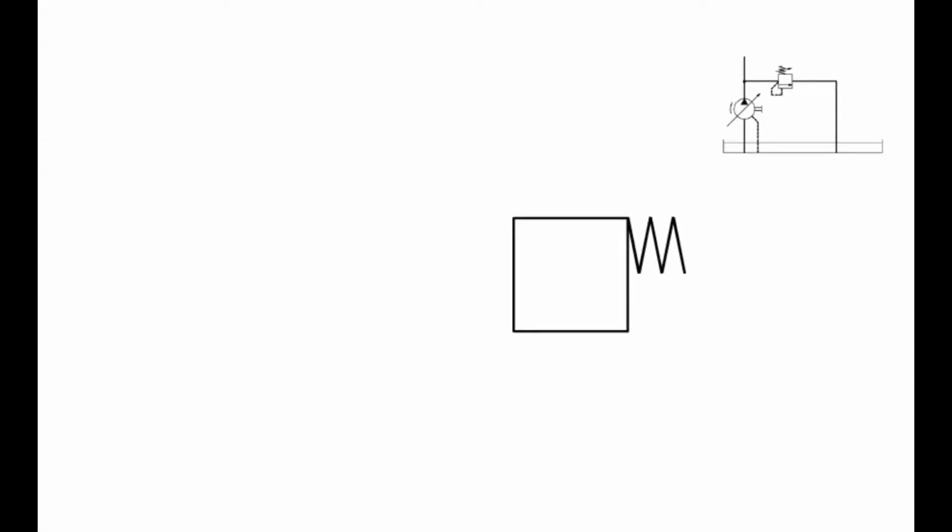In order to protect the hydraulic systems from excessive pressure and overloading, the maximum allowable system pressure is limited using pressure relief valves. Pressure relief valves limit the pressure in a hydraulic system to a specific preset value. The graphical symbol for a pressure relief valve is based on the symbolic element for a valve, a square. The actuating device of the valve is a spring, which ensures that the valve remains closed in the rest position.